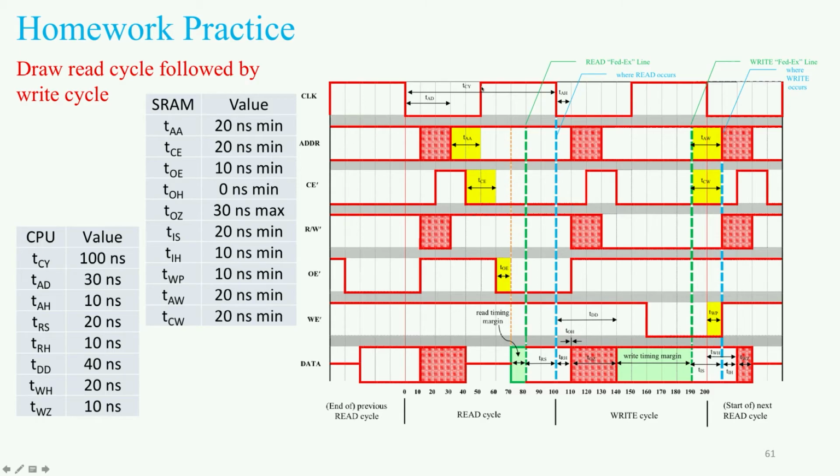So the clock transitions to the high state here at 50 nanoseconds, and then output enable will begin to change. But it doesn't change right away because, again, remember there's a propagation delay, that glue logic delay. So that 10 nanoseconds here is because of the logic delay. And then after that 10 nanoseconds, output enable flips to low, being asserted. And then we know that the SRAM is going to potentially start spitting data out.